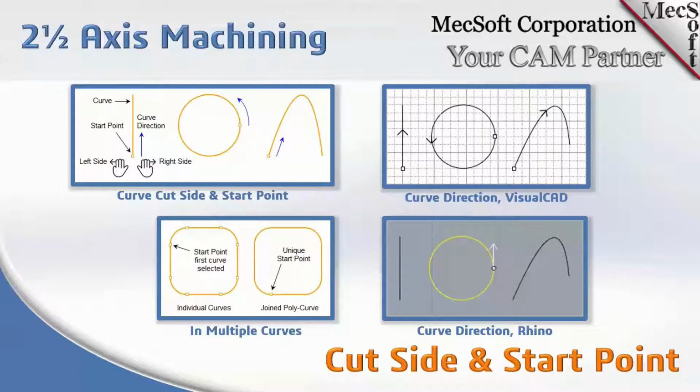Just so you understand what right and left means, if you look at the top left illustration, you'll see that we have just one line, one curve, starting at the bottom and continuing to the top. If you see the little squares there on those geometries, those are the start points. Anytime you draw a line or a curve, by definition, it already has a start point. If you draw a line from point A to point B, point A will be the start point as defined by the CAD system.